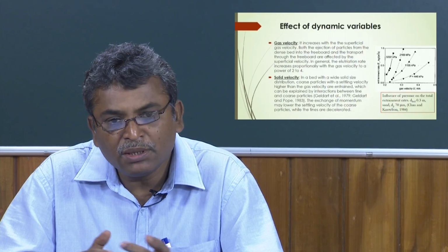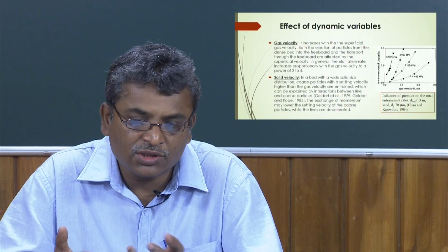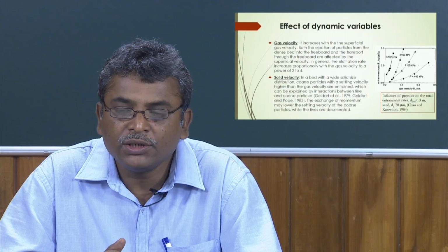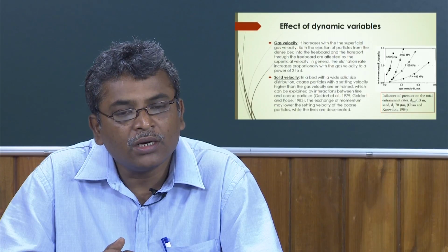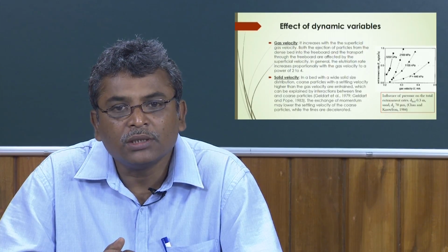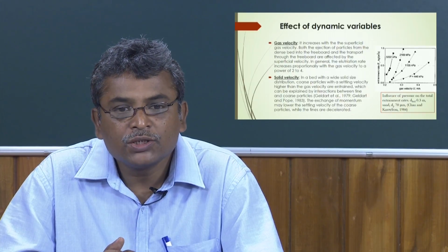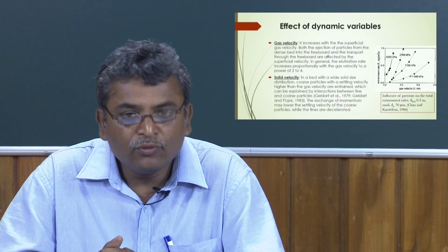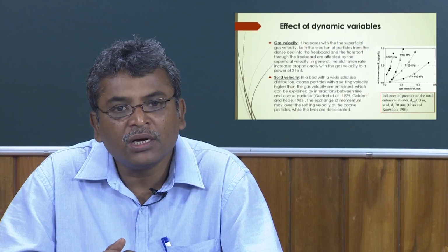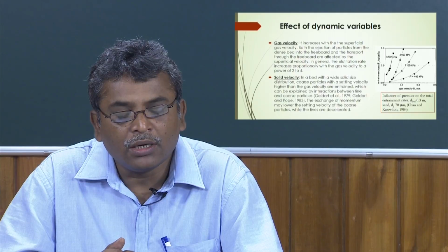The gas velocity may be considered as superficial gas velocity or actual gas velocity. The actual gas velocity equals the superficial gas velocity divided by the porosity of the bed.